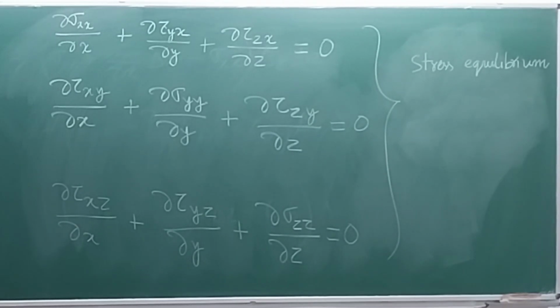That exact problem can actually be started from this thing only: the divergence of sigma is equal to 0. In fact, you can start with these stress equilibrium equations only. All that you have to do is substitute the appropriate stresses with the corresponding relations with the velocity terms.